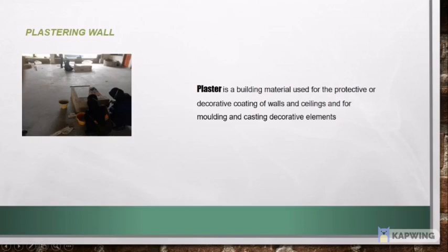What is an important aspect to be considered when plastering? When we do plastering work, it should be leveled, plumbed up, and the joint should be at the right angle at the corners or edges, so we can get a smooth plastering. Next, it must cover the non-verticality and non-horizontality of walls and columns resulting from poor workmanship and non-standard brick.